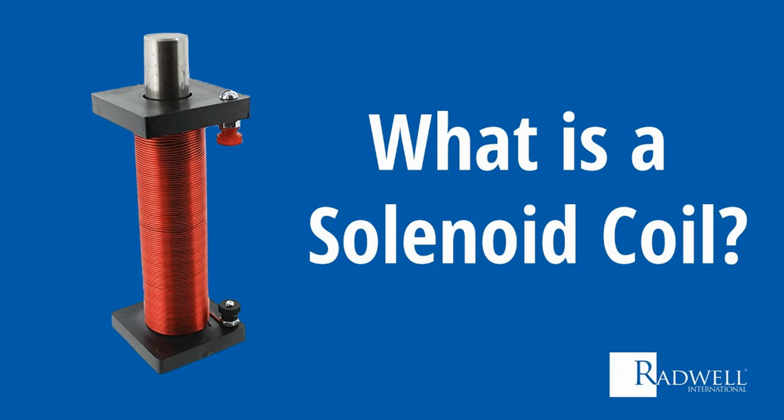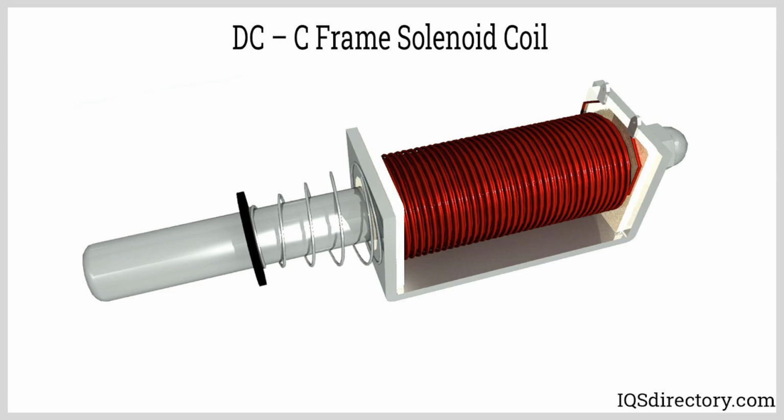Push solenoid: the core moves outward from the coil when energized. Pull solenoid: the core is pulled inward when the coil is activated. 2. Rotary solenoids. Description: these solenoids produce rotational or angular movement rather than linear motion. Operation: when the coil is energized, the core moves rotationally, typically between 25 degrees and 90 degrees, depending on the design.